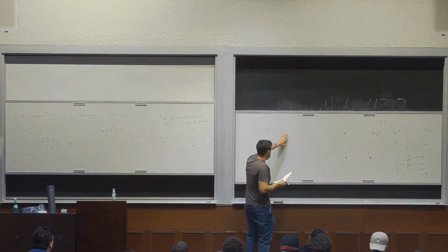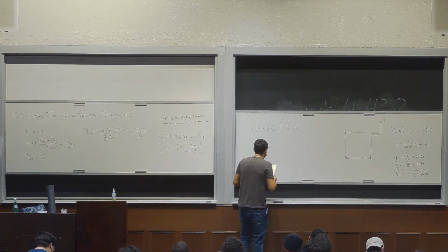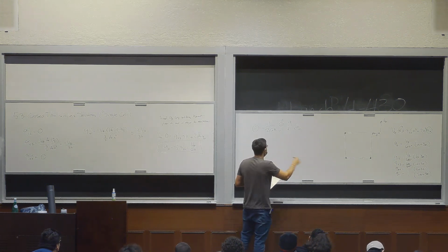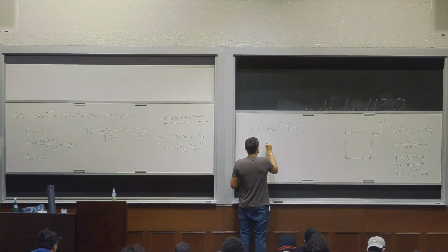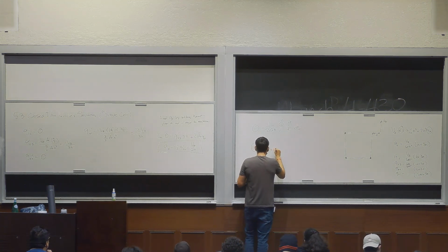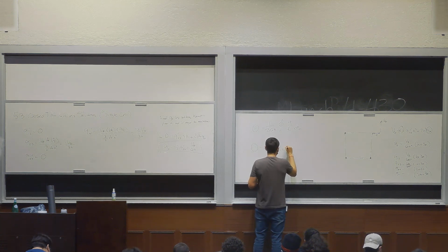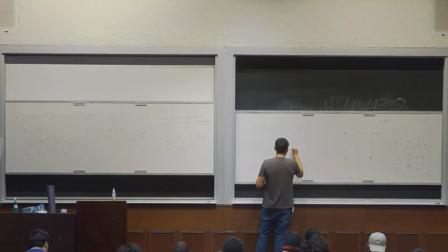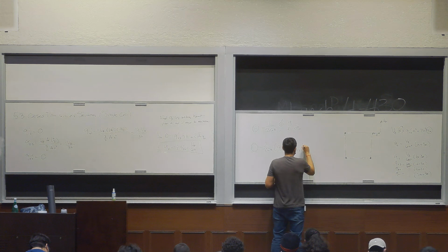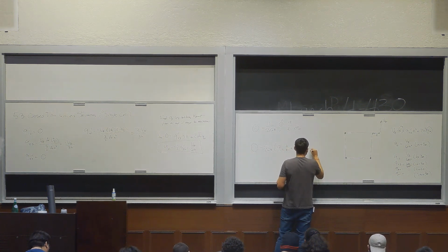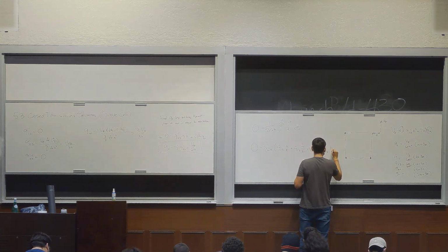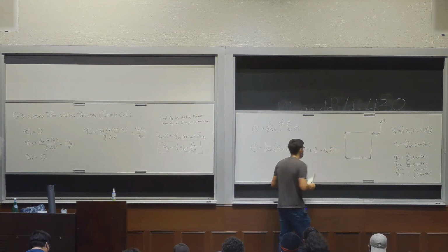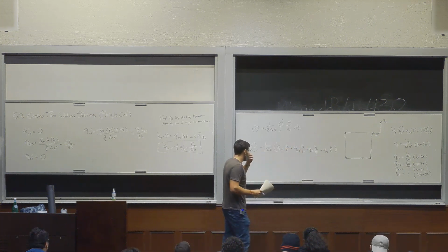Remember, these line integrals are actually really easy. So if we write it out using these shear flows, it's 1 over 2 GA times Q12 H over T plus Q23 H over T plus Q34 H over T plus Q41 H over T, going one side by one side.